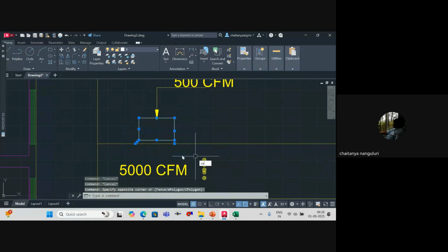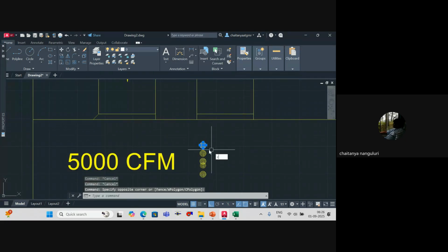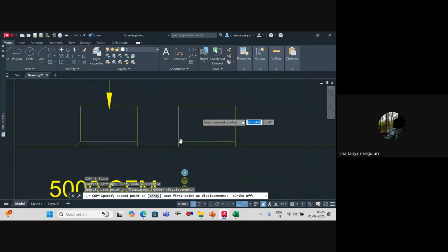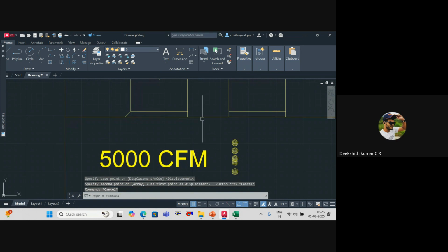What if you have not provided it? If you don't provide it, let's say your collar, you have designed it like this. If you don't provide it, what will happen? The air volume, whatever is going, that particular air can't directly take the turn. So it will take it like this. Because of that, there will be a certain reduction in the volume of air, because you have sized for 500, but a certain volume is getting wasted because of the inertia. Am I clear?